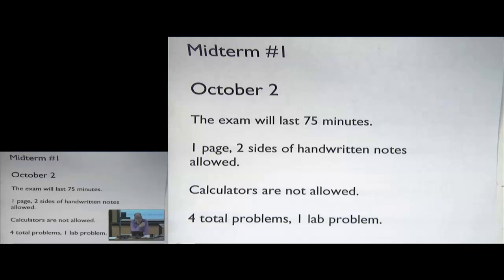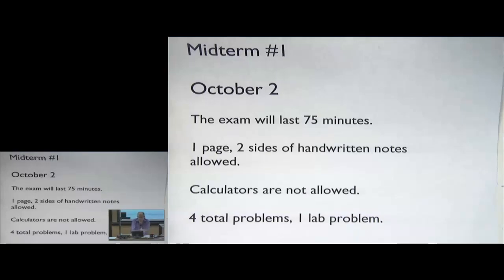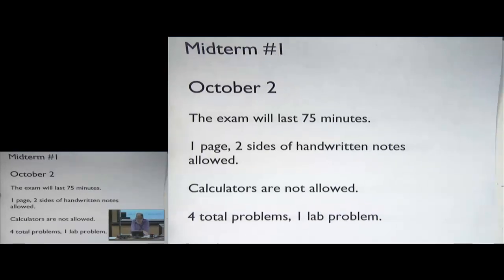What I'm more interested in is that you can use the properties and the tables to do Fourier transforms quickly without having to do the integral and everything. Because distilling the knowledge of the table into your head is what gives intuition. You're observing a signal, it's distorted, you don't know why. If you know those transform properties, you can often figure out what's wrong with the signal. I suppose you could plug it into MATLAB and compute its Fourier transform, but it won't give you any insight. So this is the reason for that. And ideally you should know the basic properties.